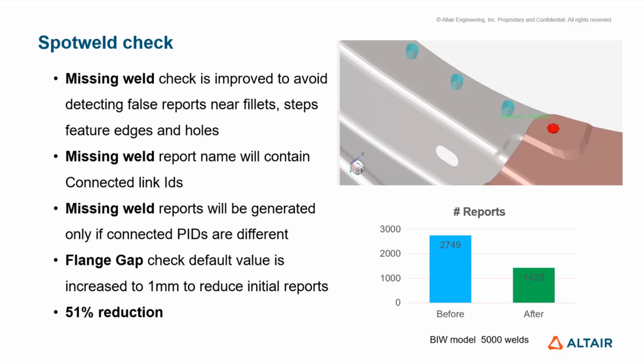Okay. With all these improvements, we were able to reduce 50% of the spot weld reports in this new release. Out of that, the major contribution came from the missing welds, where we were able to improve our logic near the fillet steps and feature edges and holes.